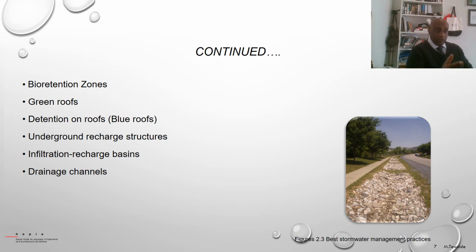Unless it is important to have a concrete canal, it's better to construct the canal with a kind of rubble like this one, so that most of the water will be allowed to infiltrate.